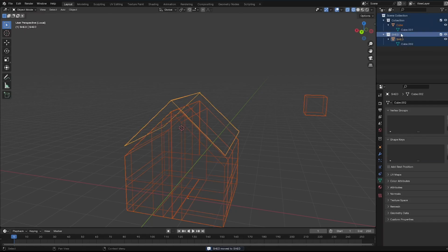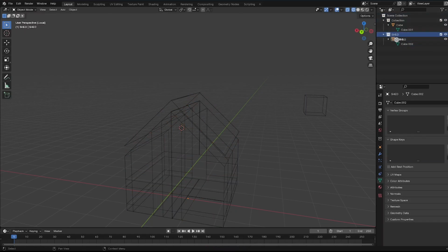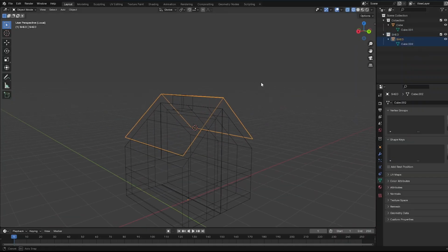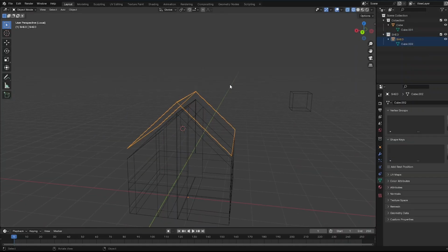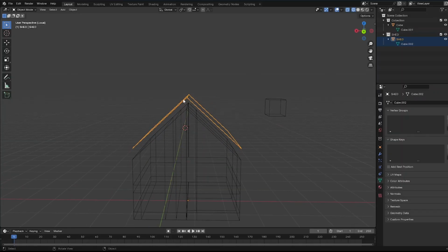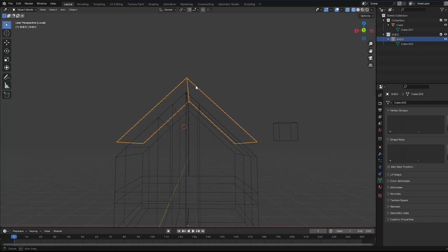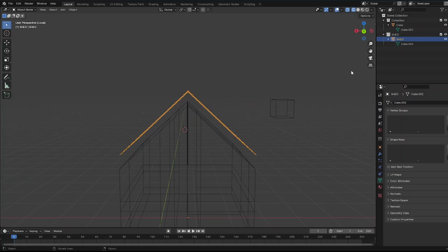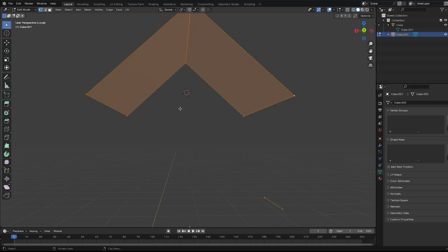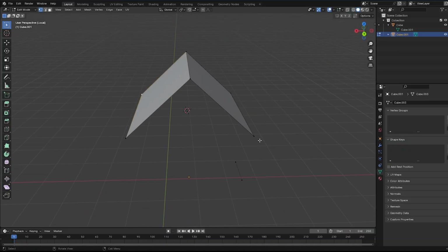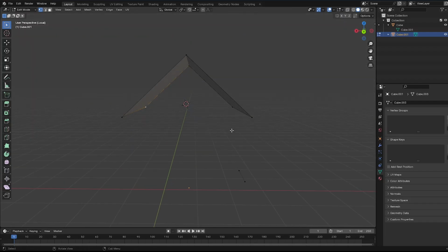So I'm going to select on A, and you'll be able to select up only this part if you want to. Select both of them up, and you can select it and also merge it however you want. So it just helps you to organize it up however you want to. Now I'm going to apply a bit of extrude on it. If you want to apply a bit of extrude on it, you have to press on E on your keyboard. As the whole thing is merged up, I'm going to increase the whole size of this by selecting on A.